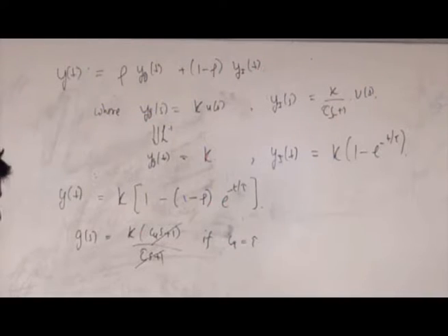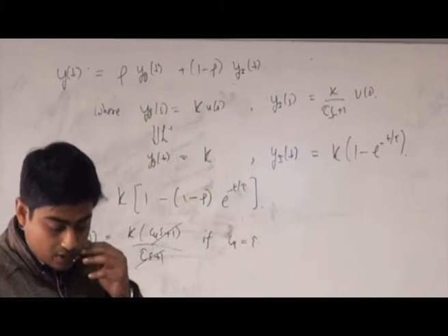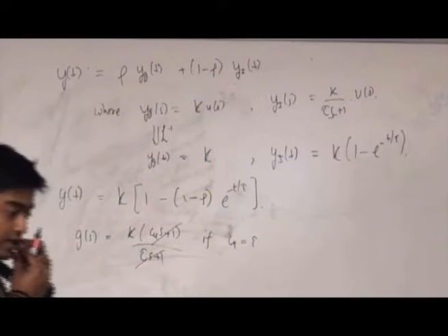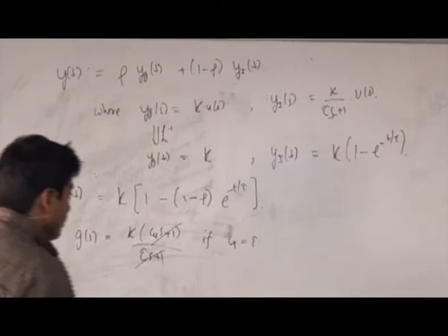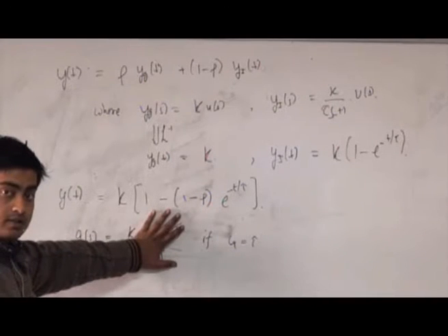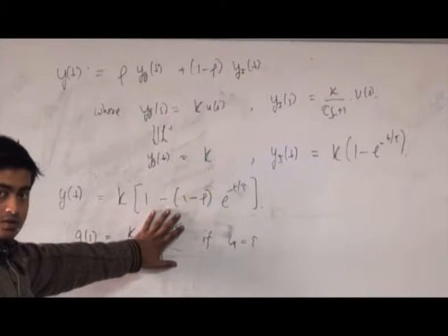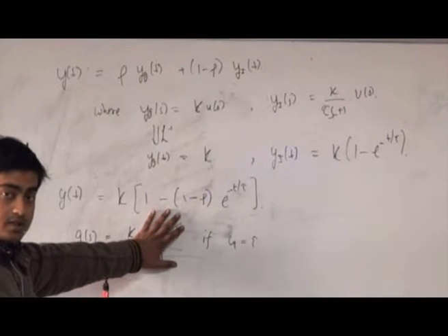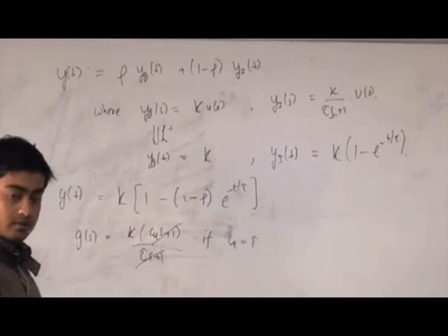Okay, you need to be very careful with this pole zero cancellation while designing your control system, because inherently what you are doing is hiding the dynamics of your system from the controller, so it cannot know what the process actually is.